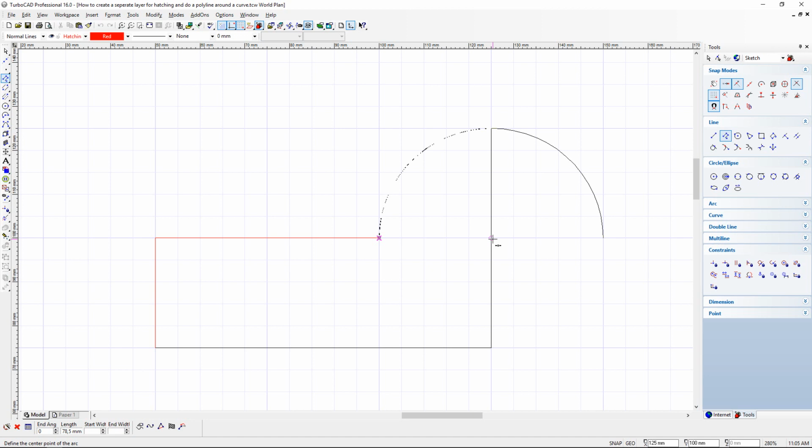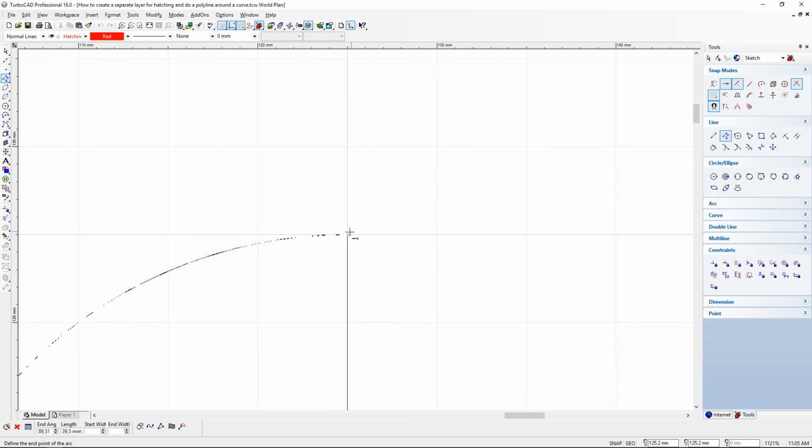But for the time being, let's just use this. I'm going to snap to the center, and now it allows me to move this arc along that edge as far as I want. So I can go all around, or I can just stop here at the end where I am. And then if I'm happy, and if I zoomed in and made sure I've snapped it, do you see that little pink diamond that's appearing there? That is to show that it's actively snapping to that point.